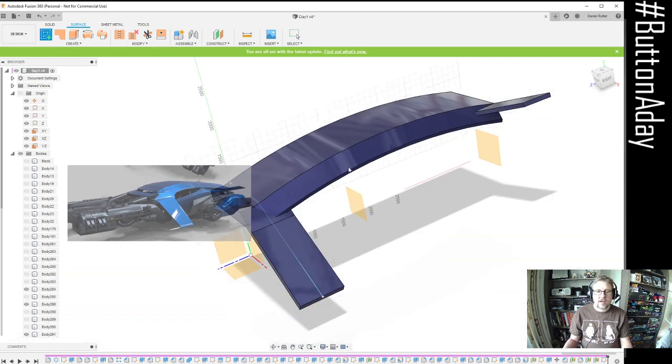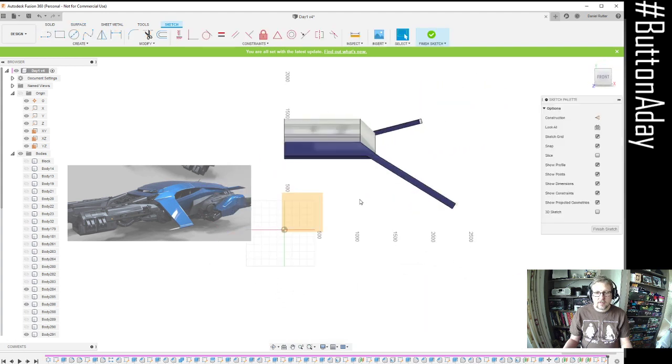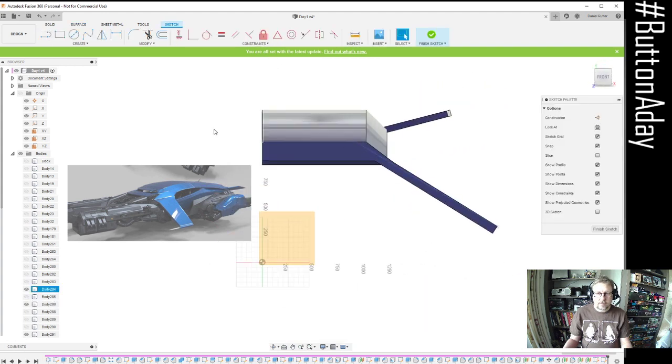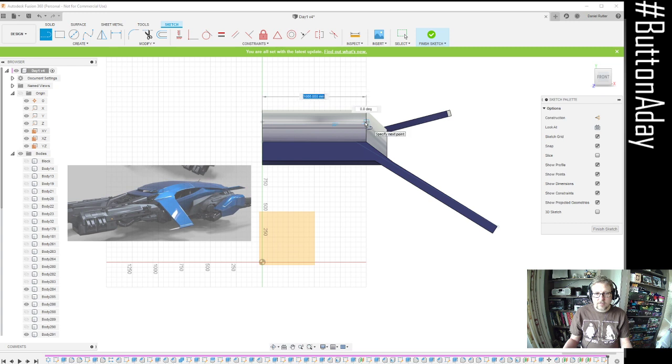Okay, so we're going to create another sketch. Click on this middle one. It's usually a good idea to try and put the same number of points into your sketches, so when you morph from one to another it has a much easier job of saying, okay, this point of this line would look best lined up with this point.